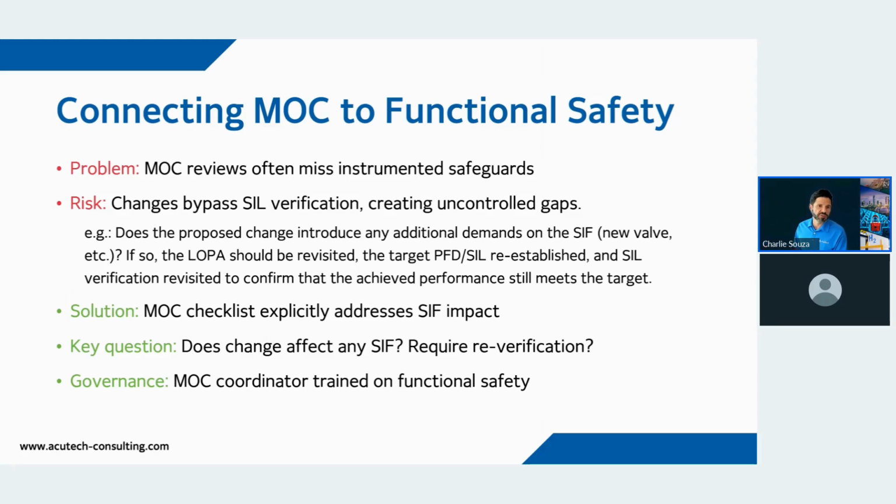A lot of times, if the person doing the MOC is not trained or familiar with functional safety concepts in terms of how fast the safety function needs to respond, a mere change in set point may now require that safety function to respond quicker.